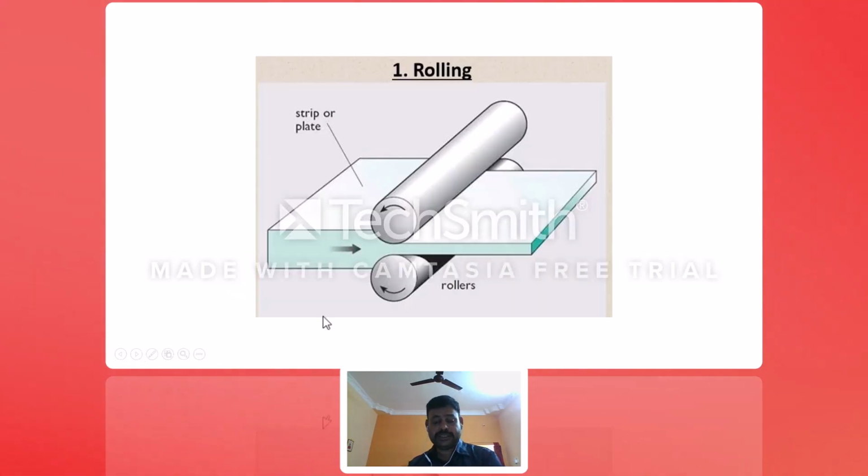Already I said sugar cane crushing, right? You have an upper roll and a lower roll. In between them, you insert the plate. Before inserting, it has this much thickness. After inserting, the thickness is reduced. Here the volume remains constant. Whenever the thickness decreases, the length is extended, so overall the volume is constant. This is called the rolling process.